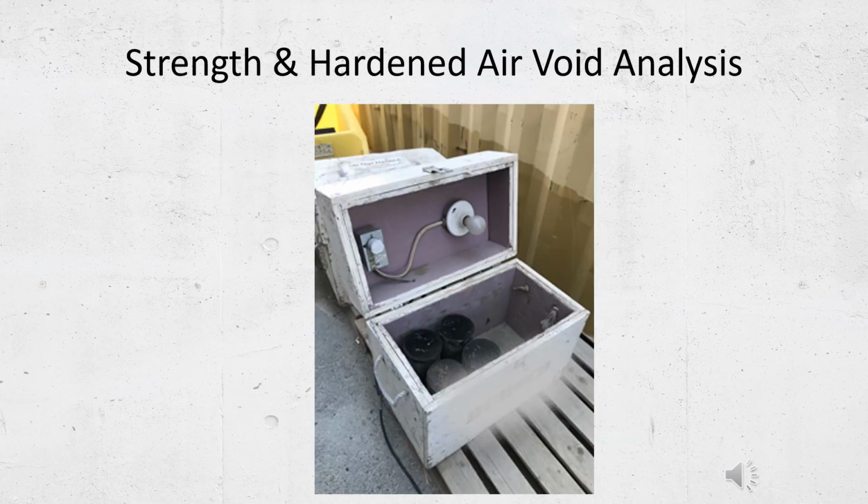The 5 concrete cylindrical test specimens cast to represent the concrete produced that passed the yield and within batch uniformity tests should be handled and cured in accordance with CSA A23.2-3C. All test specimens cast should be tested by a third-party certified independent concrete test laboratory to determine average compressive strength of 2 cylinders at age of 7 days and 2 at the age of 28 days. The 5th cylinder cast shall be reserved to conduct hardened air void analysis, confirming the concrete produced is within air content, air void spacing, and specific surface limits for Class C2 exposure concrete.